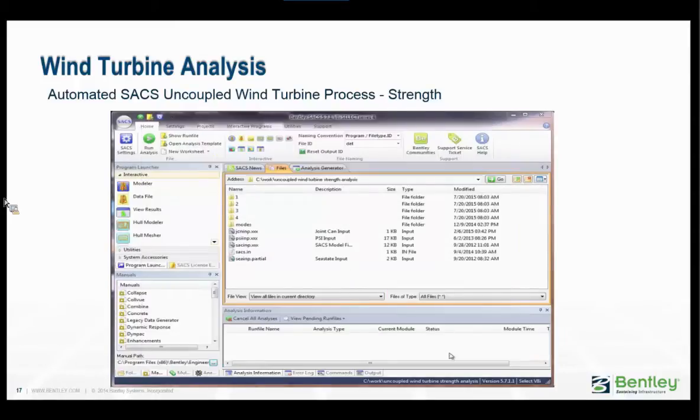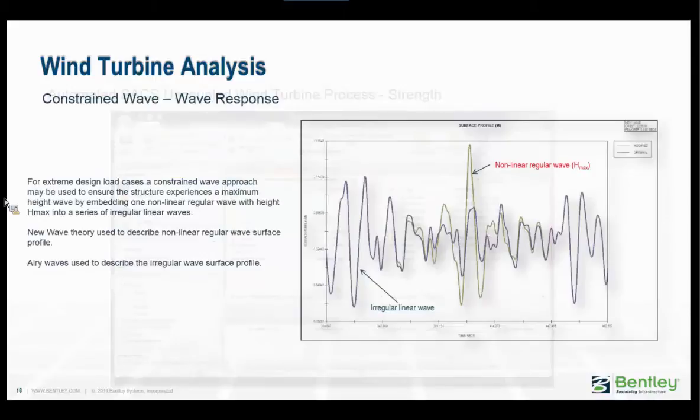Okay, so moving on a little bit, to generate the load cases to design for an extreme wave, you have a couple of options. The first option is to run a multi-seed analysis, usually up to 6 seeds are recommended, and then average out the actual internal loads to give you the critical unity checks corresponding to these.